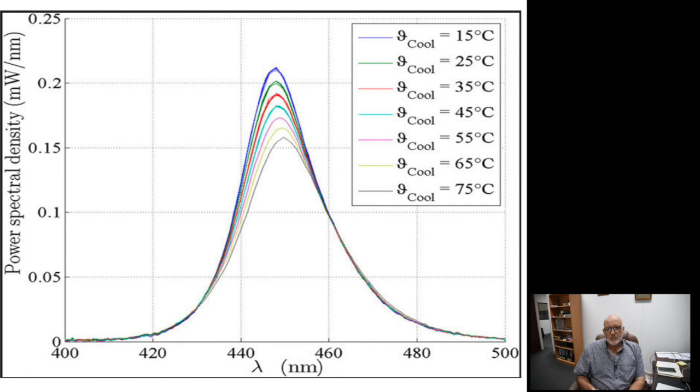So on the first slide, what I'm going to show you relates to the degradation of output, the reduction of light. The chart is a two-axis chart. The x-axis is wavelength, and on the y-axis is spectral power over wavelength. This is the surface illuminance over colour. And as you can see, this LED is peaking roughly around 450 nanometers, so it's a royal blue LED. And what are we looking at?